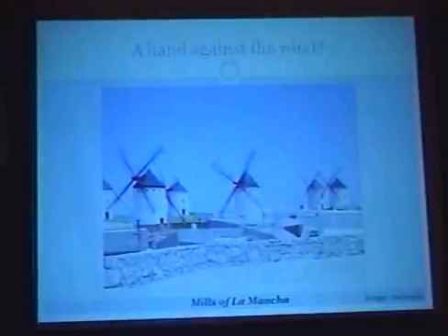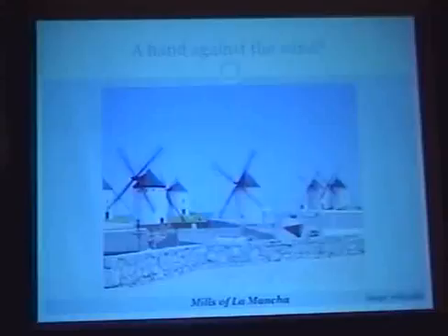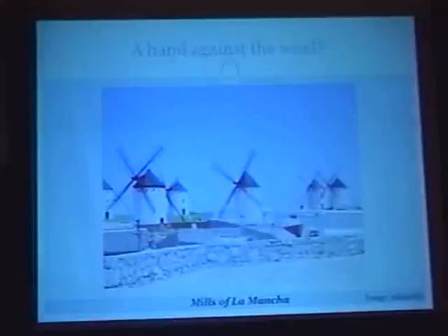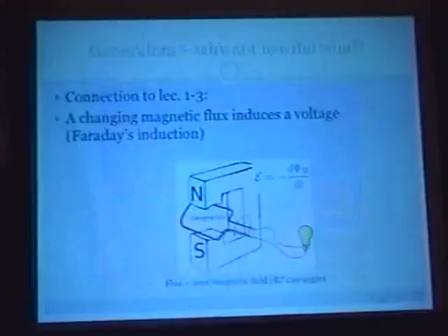Also note that this doesn't really look like a modern wind turbine. These look more like the wind turbines you'll see in the fields today that generate electricity. And these might not make a lot of sense right away because, from the point of view of imagining your hand out the car window, these seem to have sort of a flat hand to the wind. You might think that you should have vanes that are aligned more or less along the direction of the wind, but maybe tilted to give you some lift. But instead, you see that these look practically flat. So I want to spend some time talking about how to think about these lift-type turbines, because the mechanism is a little bit more subtle than drag, which I think is a lot more intuitive.